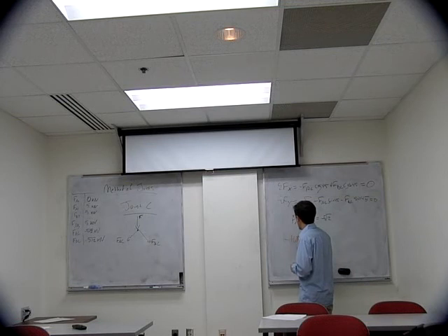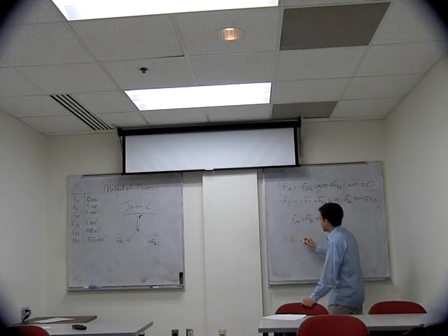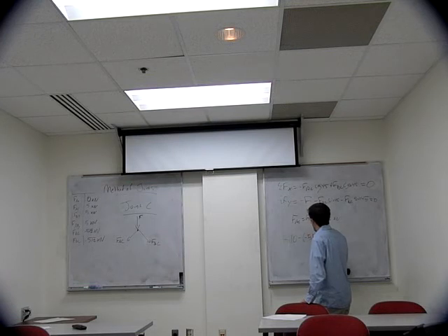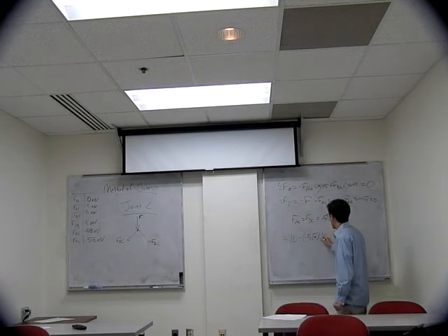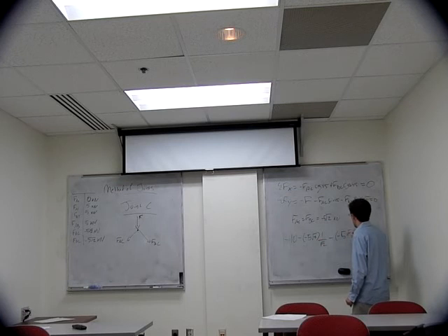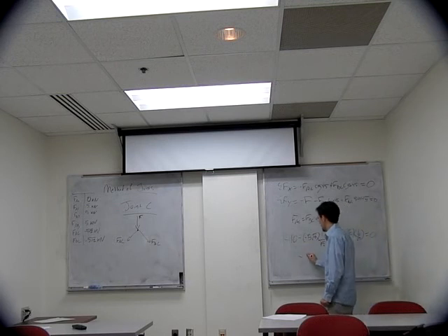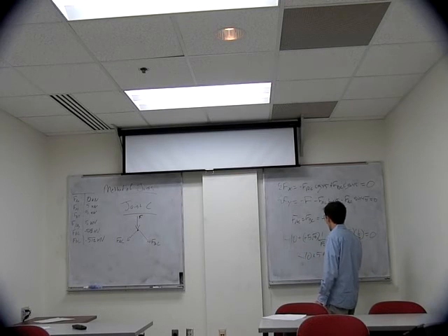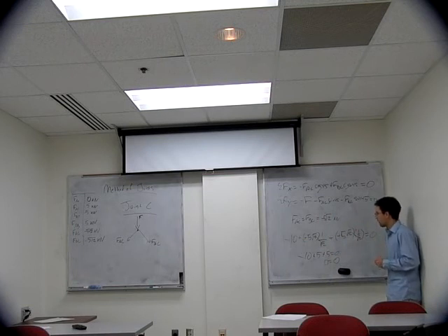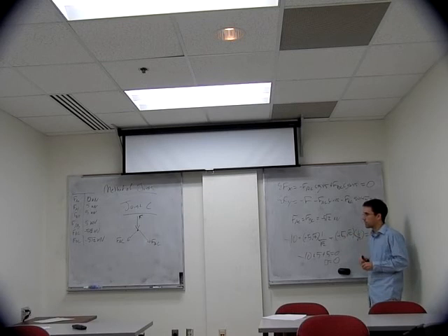So we know that our applied force was 10 kilonewtons. FAC was minus 5 times the square root of 2. Sine of 45 is 1 over the square root of 2. FBC was negative 5 times the square root of 2, times 1 over the square root of 2, is equal to 0. All the square roots of 2 cancel. We get negative 10. We get double negatives, so we have plus 5 is equal to 0. 0 equals 0. So here we see that all of our numbers check out.